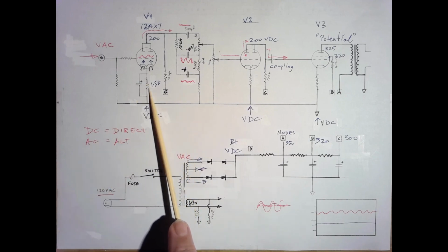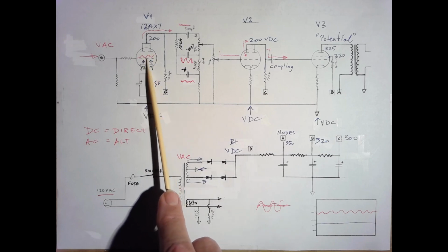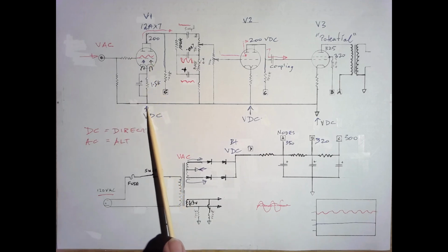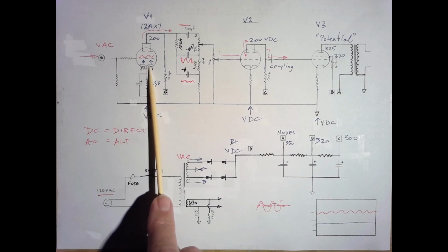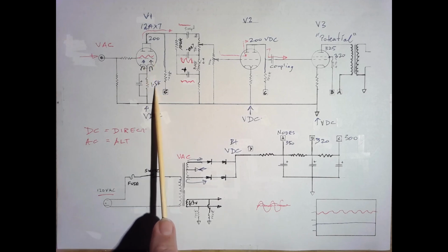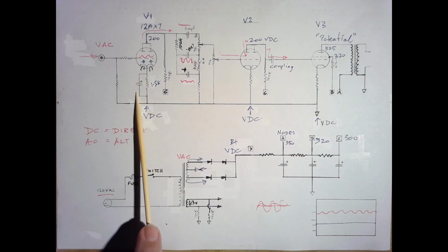So we also have our cathode resistor here, and people often talk about cathode resistors in terms of biasing the tube, and the size of this cathode resistor then determines the flow of DC electrons up onto the cathode, so that the availability is greater or less depending on this resistor here. We can also talk now about the bypass capacitor.